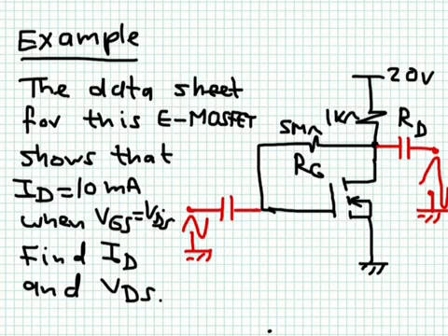But now we are worried about the biasing, and remember that the biasing will determine for us the transconductance, how the gain is going to be. If I apply a small change to VGS, how will that be reflected in the change in IDS? So the biasing is very important, so we only focus on the DC part. Because we connected the drain to the gate and there is no current flowing here, then indeed VDS is equal to VGS. The drain and the gate have the same voltage.